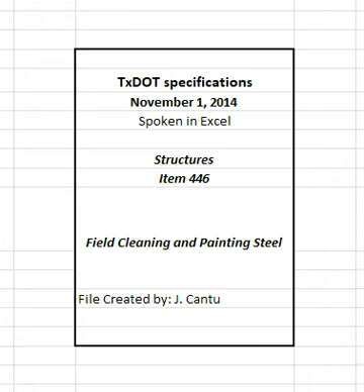4.7.1 Hold points. No work may proceed beyond the listed hold point until the engineer has reviewed and given provisional approval. Provide the following hold points at a minimum. At containment completion. Following any surface preparation. Immediately before each coating application. After coating application. After each coat has cured, and after preparation of areas for repair.